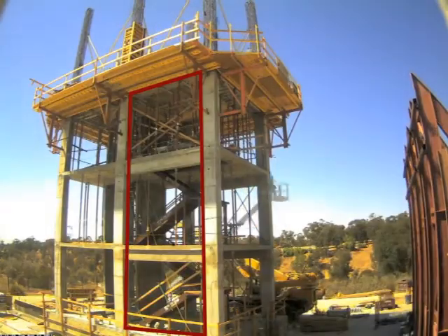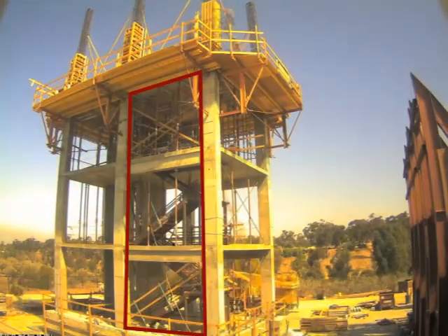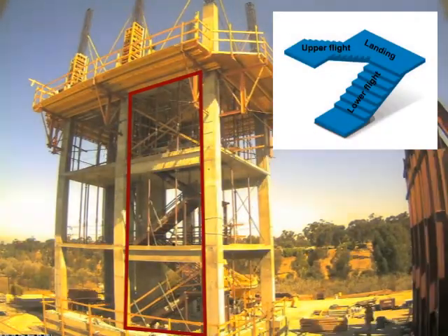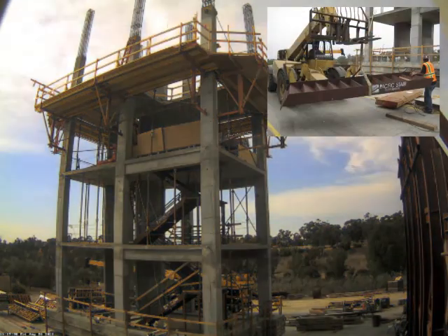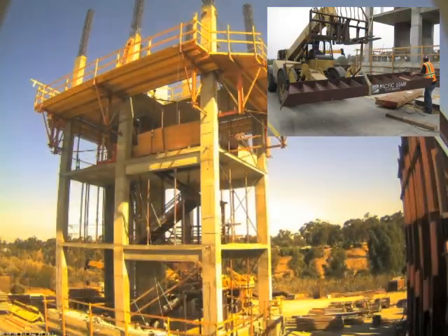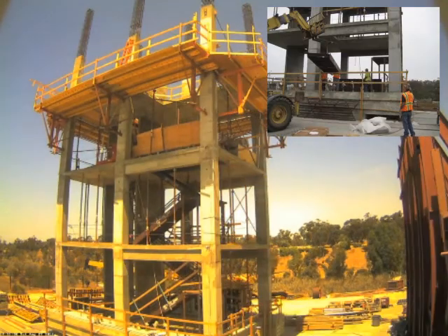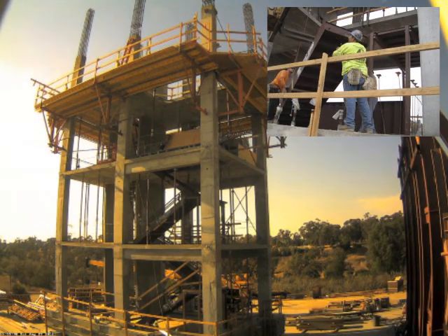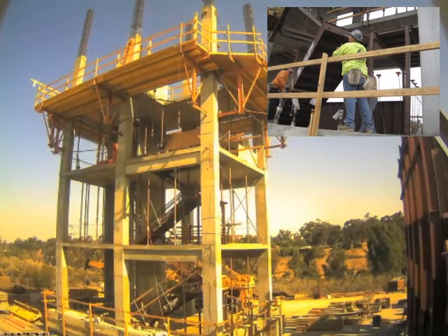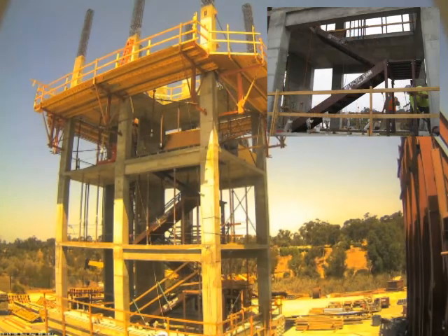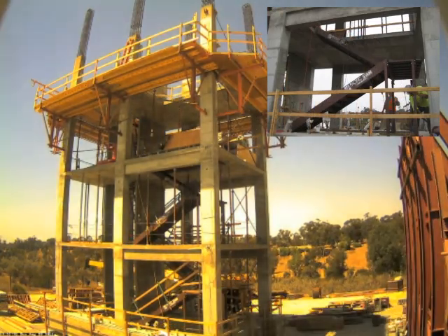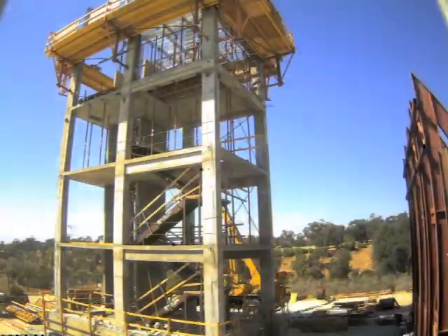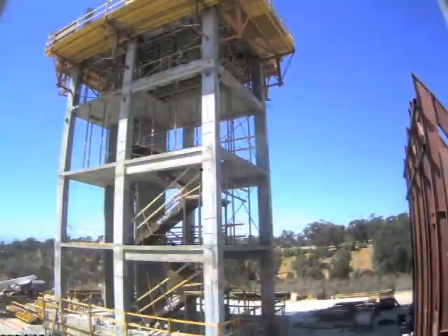In addition to structural formwork providing access to each subsequently constructed floor level, prefabricated metal stairs were installed at each level to provide access to the upper levels. The stairs are built off-site and then moved to the site for installation. Stairs are installed in 2 phases. During the first phase, the skeleton of the whole structure is not complete, and the stairs connect only the first 3 lower floors. After the completion of the skeleton of the whole structure, the second phase of stair installation begins. Stairs connect the upper 2 floors in this phase. This method is continued with slight changes for the subsequent upper floors.